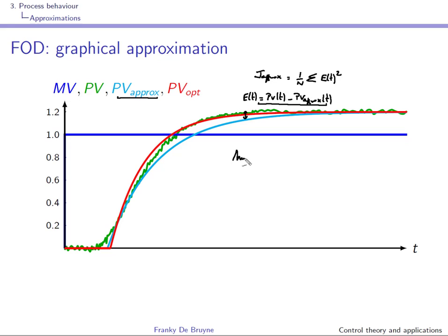And this leads to an optimization problem where you minimize an identification cost that looks like that over Kp, t bar, theta bar, right? And this will try to minimize the discrepancy between what comes out of the model and what comes out of the experiment, right?